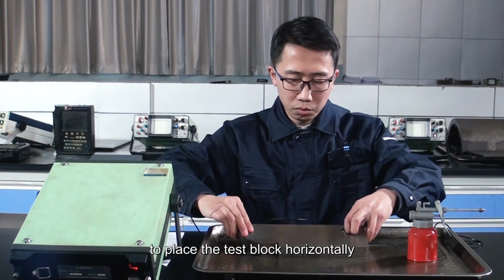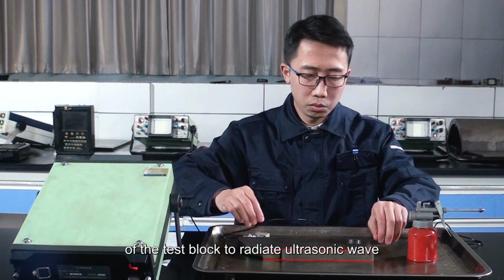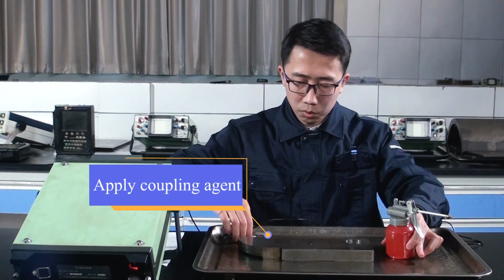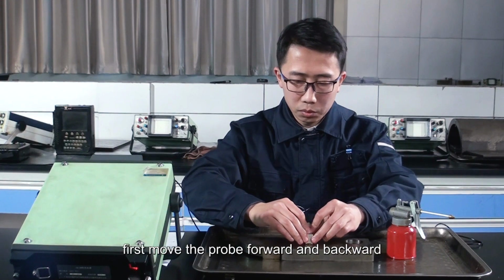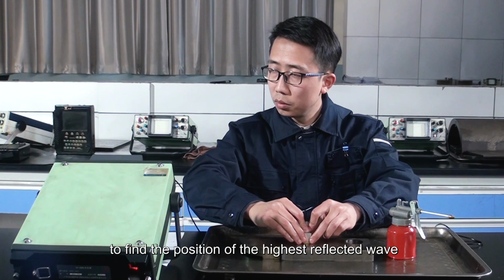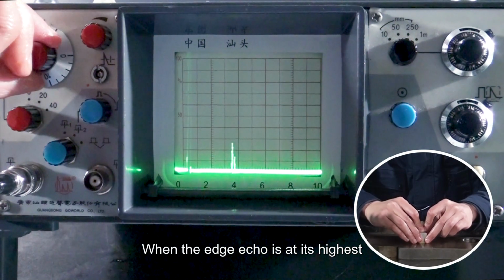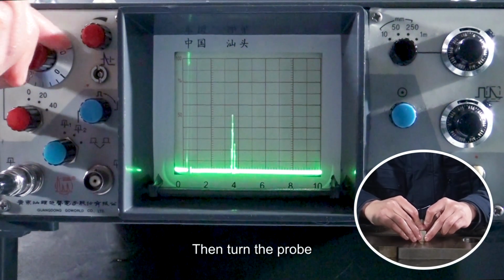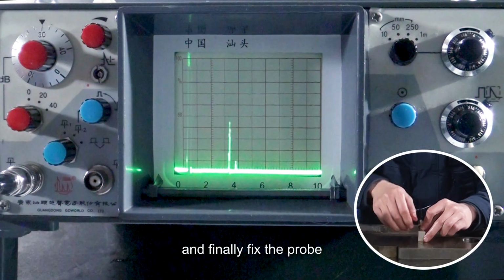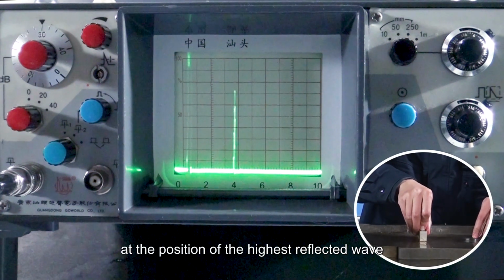Finally, the measurement method of the sound beam deflection angle of the angle probe is to place the test block horizontally and make the probe aim at the edge of the test block to radiate ultrasonic waves. First, move the probe forward and backward to find the position of the highest reflected wave. When the edge echo is at its highest, turn the probe until the highest reflection position is found, and finally fix the probe at the position of the highest reflected wave.